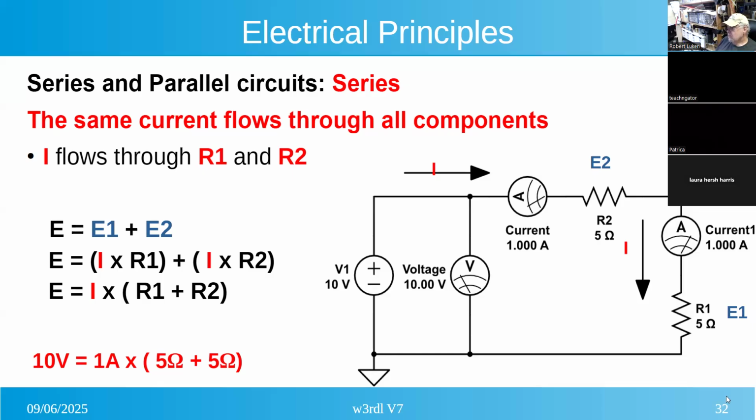They're equal, right? 5 volts each. They're both equal, so they're 5 volts. So it has to add up to the supply voltage. There's a thing called Kirchhoff's voltage law, which says the voltages around a circuit must add up to 0. We have 10 volts coming up, and then we have an opposing 10 volts in the opposite direction, so they cancel out. So it's 0 around the circuit.